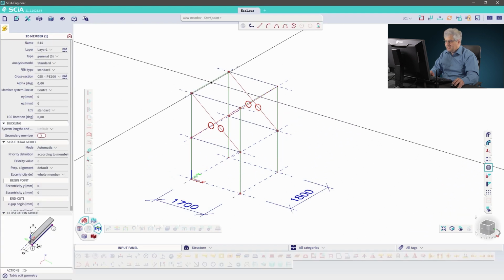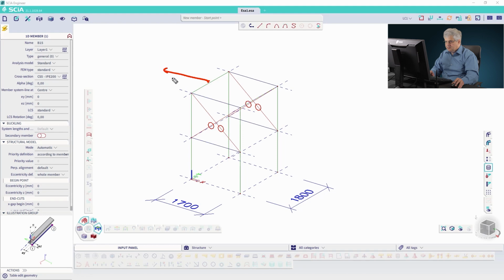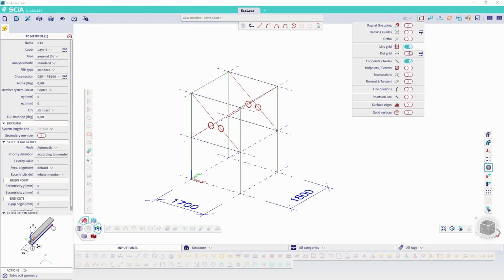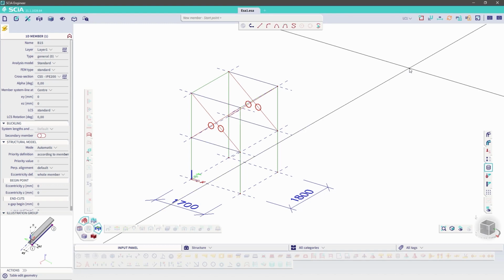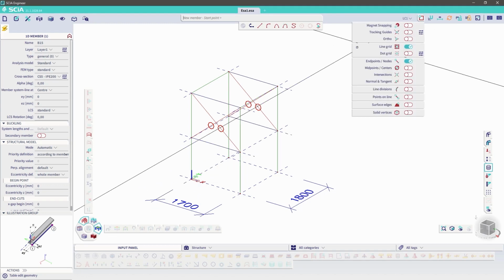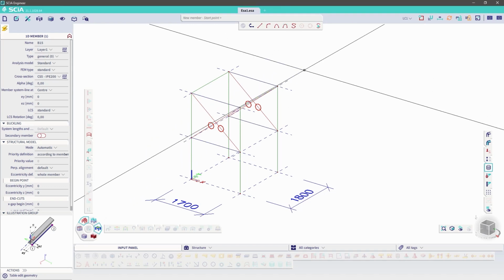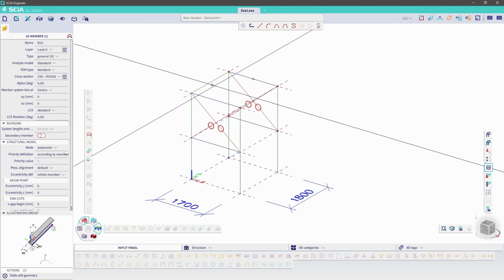Okay. Save it. And I want to start 2 meters from this point. So therefore I need snap point for the middle point. This is this midpoint, and I need also tracking. This is F7. So you can use midpoints, and I activate F7. It's tracking. So I start with this point. This will be my reference point.